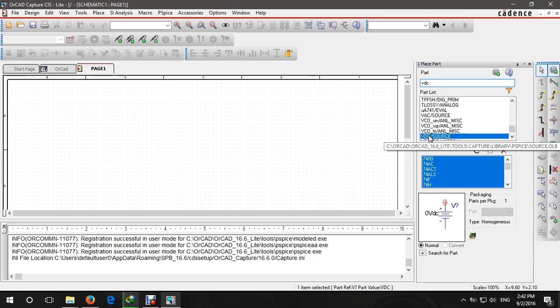Okay, so we have a voltage source highlighted, so we double click on this and we have it appearing here. So let's say we want to rotate it, so we press R once and it's rotated. Let's say we press R again, rotate it again. Okay, so R rotates it basically. To place the component you just left click, and to deselect it you press escape. Okay, that's good. Now I'm not going to assign voltages or names to that source yet.